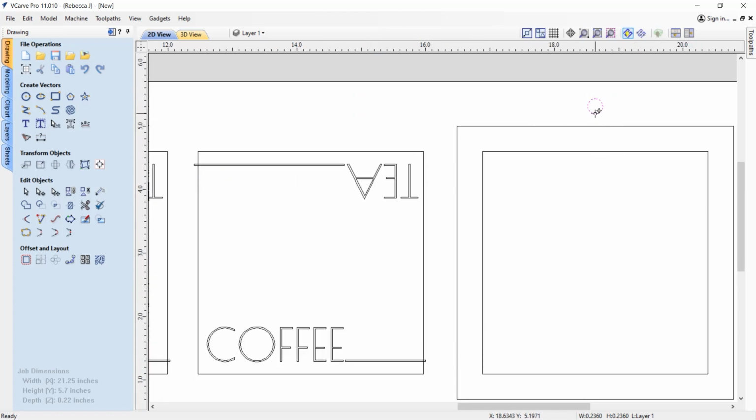So I'm going to move that so it snaps exactly at the halfway point of the top portion of our coaster. And then what I'd like to do is move it up the y-axis by a very small amount, and that's just to ensure that we give a little bit of wiggle room for our coasters to sit inside of those pins.